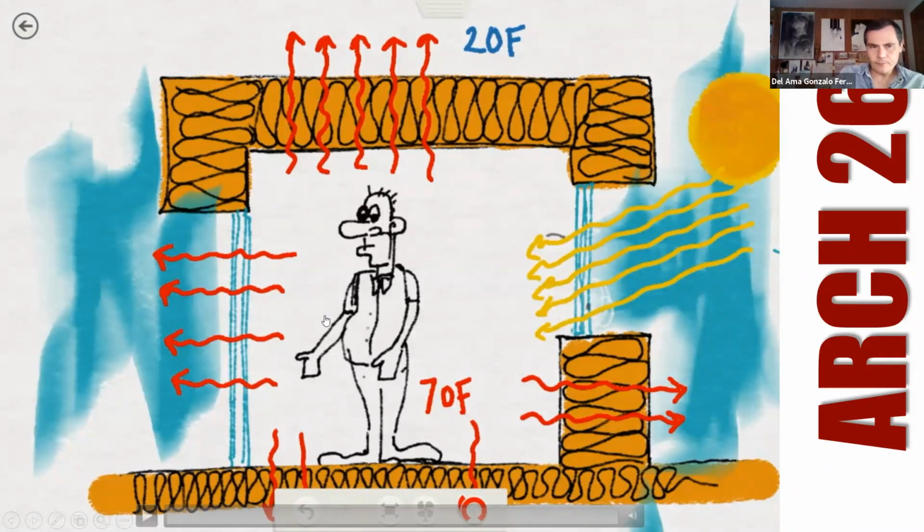So if this is a south-oriented window, because the sun in winter is mostly in the south, it rises in the east, it sets in the west. This is not true, by the way, but most of the daytime, we have the sun in the south, heating the south facade. So if we design good windows with the right orientation, we can make the most of this solar energy. On the other hand, if we have windows in this north elevation, there will be a lot of heat losses. So designing windows properly can save a lot of energy.